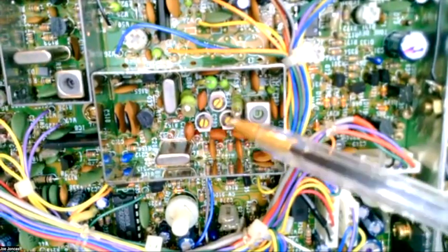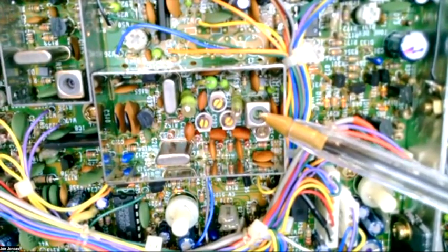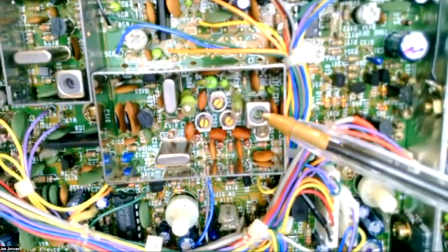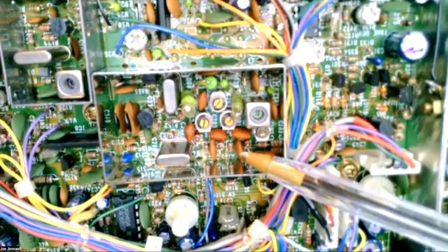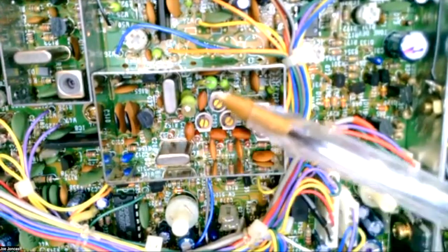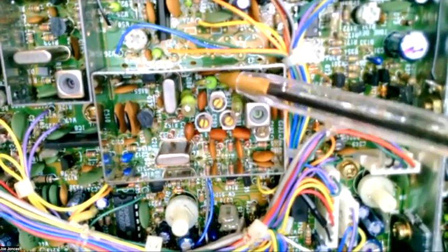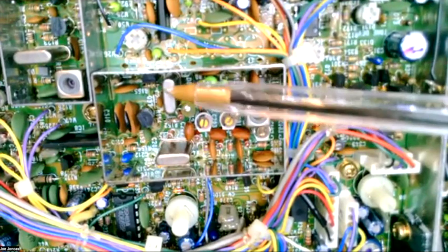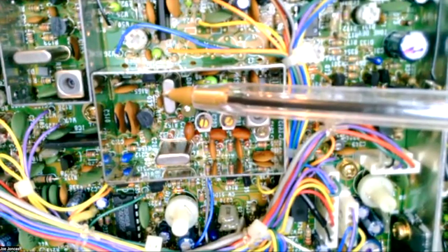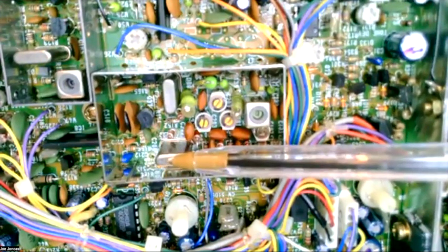Here are 3 trimmer capacitors. Here's a transformer or a coil with an adjuster. That one has, you can see down inside there's a little slot. Here are capacitors. See these capacitors here? Those are disc capacitors. These green things are resistors. Here's a crystal and here's a crystal. These, with transistors and stuff, they oscillate. And what's nice about these crystals is they lock you to a very specific frequency.